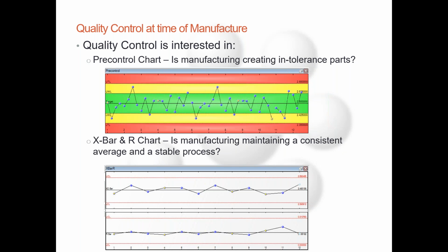The mathematics is not hard, but it's very labor intensive. So your internet's going to be your resource there. It's going to either be cheap or, if nothing else, it'll at least tell you how to do it yourself. But you being the operator of the machine, you want to be more familiar with what X-bar charts look like than how to necessarily manufacture them yourself.